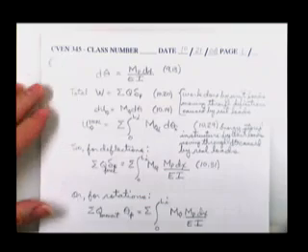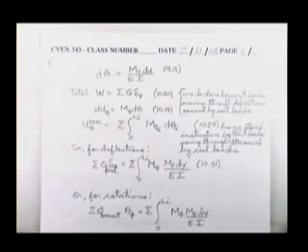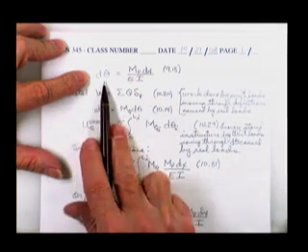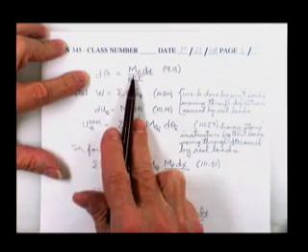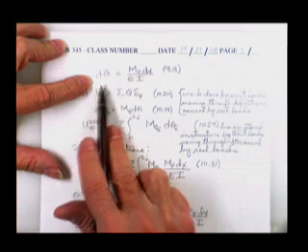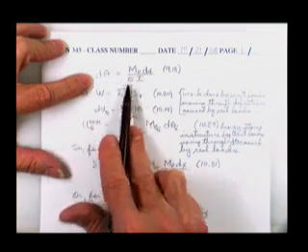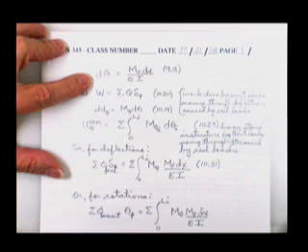Now, I stole some of the equations out of the book just to kind of summarize them. I've learned my lesson. Don't copy them out of the book and write them down because I get half the terms wrong thinking about something else. Equation 9.13, we related how a beam bends to how much moment you applied. I believe the original equation said d theta dx is equal to M over EI, which was curvature.